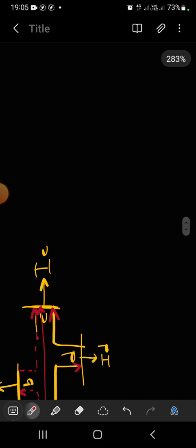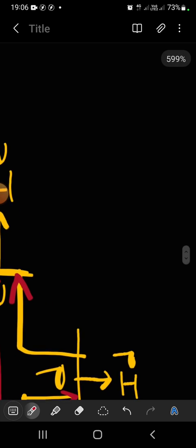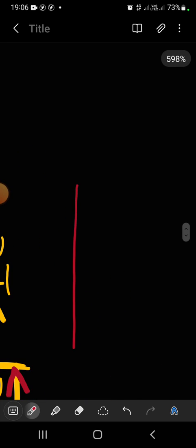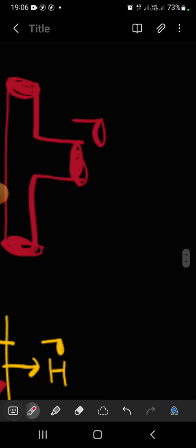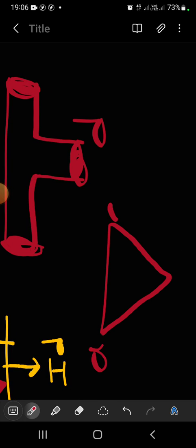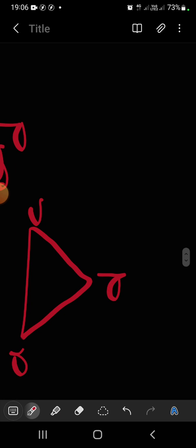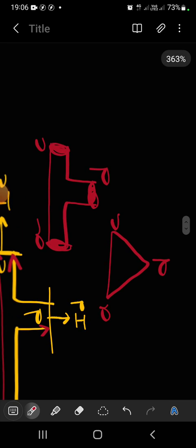The second step that we need to do now is convert the Zs to Y configuration. Let me show you why we said they're in star. I'm going to draw, this is Z, this is A, and this is C, and then you have D there. Now all these Zs are linked with a bus bar, so you end up with something like this: A, C, then D. That's your three-phase delta connection, not star, I mean delta connection.